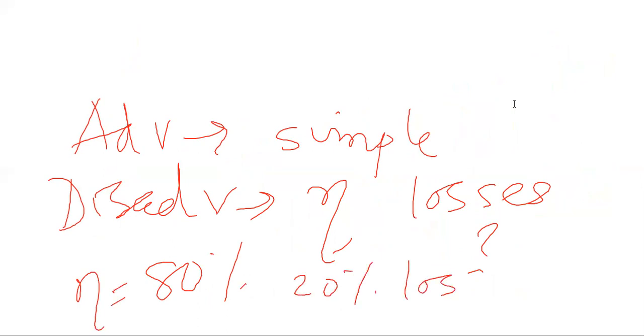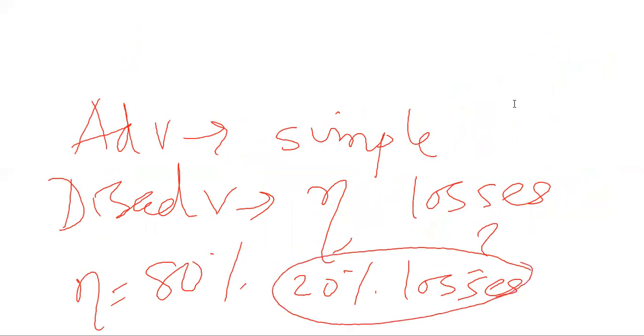So from the direct method, if I find an efficiency equal to 80%, you can at the most say that 20% are the losses, but you don't know where these losses are happening and why the efficiency is so low. In order to know where the losses are happening and to do an intervention to improve the energy conservation of the boilers, you need to pinpoint the losses, find where they are happening, and then calculate the efficiency. That method, where you find the losses and then calculate the efficiency, is known as the indirect method.